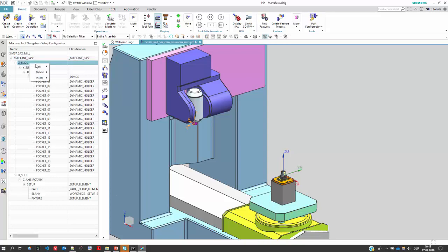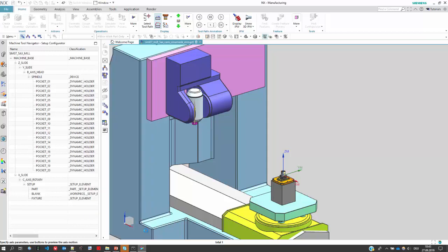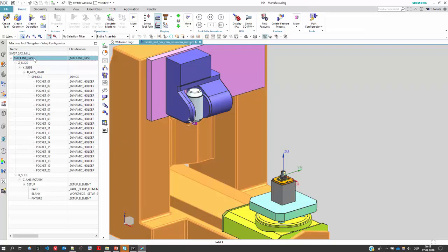And this is the setting within the initial values here. Here you tell it what's the offset between your tool mount position and the machine 0 position. We make it very simple in our out-of-the-box examples. We very often simply add the machine 0 into the spindle. So therefore all axes are in 0 position and we don't need to add any initial values in here.